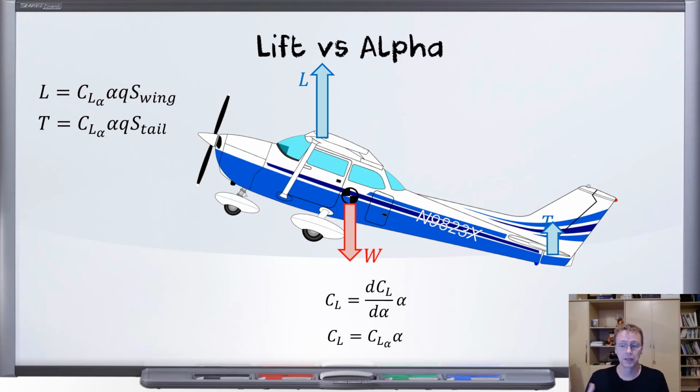We have the ability to mount our wings at whatever angle we want, right? We can mount the wing pitched up a little bit so that the pilot can fly straight and the wing will still have an angle of attack. And we can mount the tail up if we want extra lift off the tail, or we can mount the tail down, hint, hint, if we want less lift off the tail. But for this beginner's introduction to how we're going to do stability, let's assume that it's nice and straight and symmetrical, and that it's the same airfoil for both.